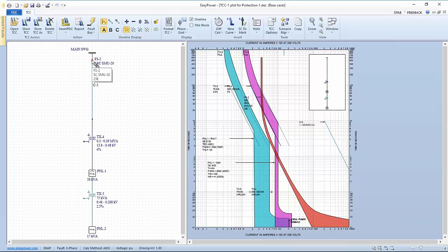Now, you'll notice that there's a color coordination. The easiest one to see is this fuse is kind of magenta or red, and it correlates to this curve here, which if I look at is, of course I got to pick out the right label. Is this fuse, and so I've selected in my options for my plot to coordinate the breakers or the protective devices with their curve.